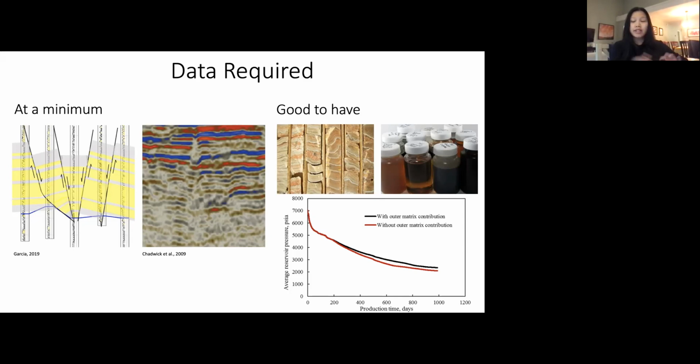It is also good to have fluid samples from the reservoir. In CO2 storage, and in drilling in general, there is something called mechanical integrity testing. One of the components of that testing is to check whether the cement will hold, so that fluid does not get through the well from the cement itself. You can do experiments on how the CO2 reacts with the fluid, and whether that interaction will compromise the integrity of the cement and cause leakage.